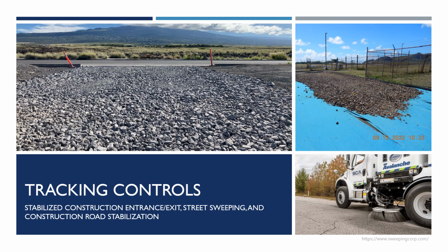The stabilized construction entrance and exit provides a pad where coarse material can knock the fine material off of tires before exiting onto pavement. The minimum dimensions expected for stabilized construction entrances and exits are 50 feet long, 30 feet wide, and 12 inches deep. In cases where sediment trackout is still observed, increased street sweeping of adjacent roadways or other paved areas may be implemented to supplement stabilized construction entrances and exits.